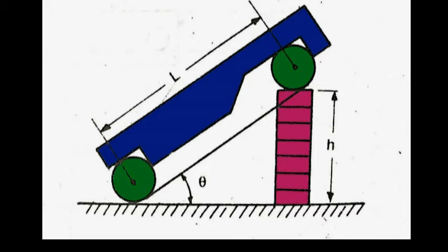Above 45 degrees, the effect becomes progressively more significant, and generally it is not preferable to use the sine bar for measuring angles larger than 45 degrees if high accuracy is required.